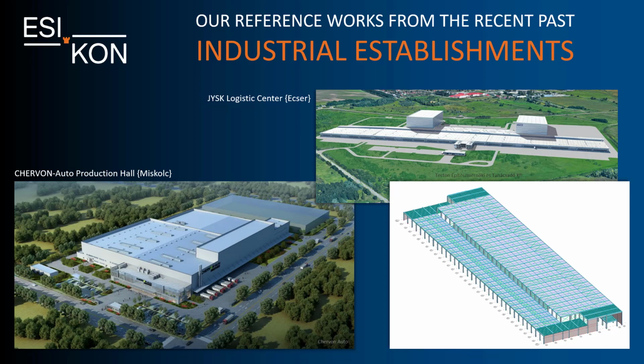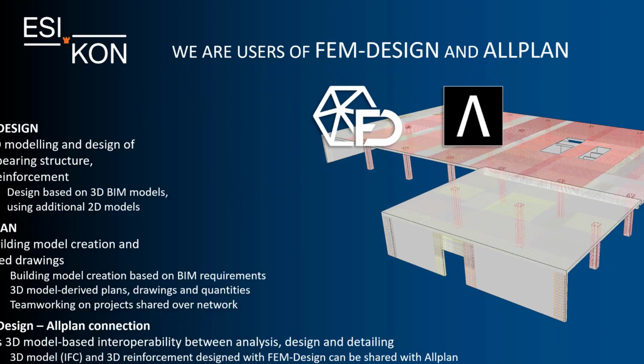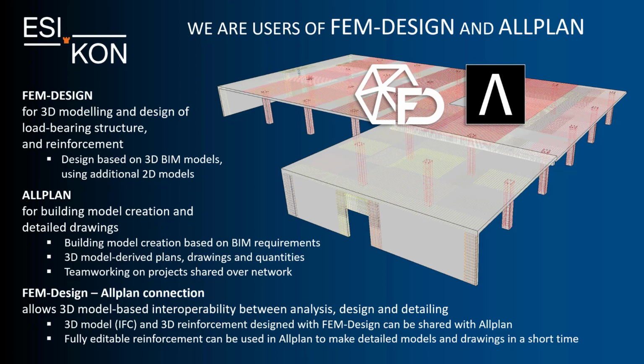In our practice, we use FEMDesign for 3D finite element modeling combined with 2D models to calculate the inner forces and displacements of the elements and to analyze the structural behavior during seismic action. We also use this software to calculate sufficient reinforcement and to check the utilization of steel structures.